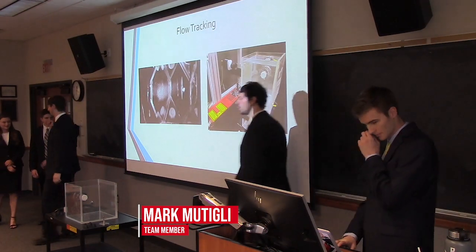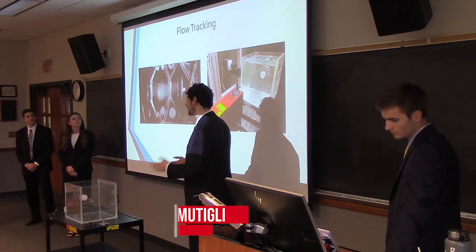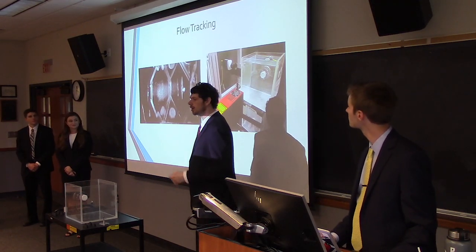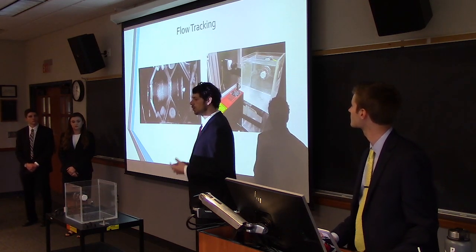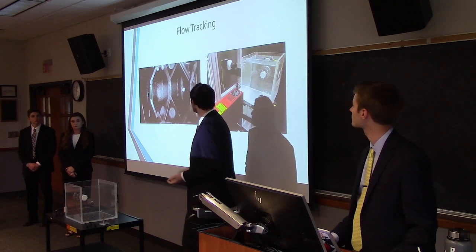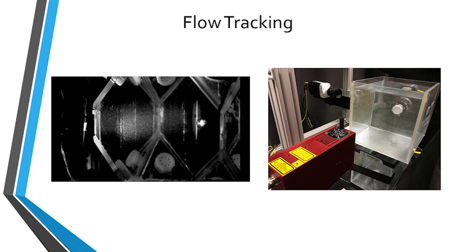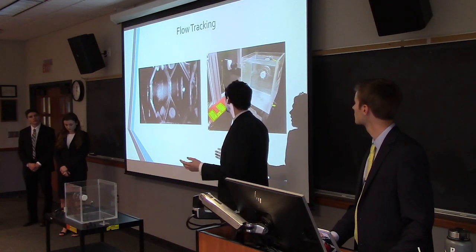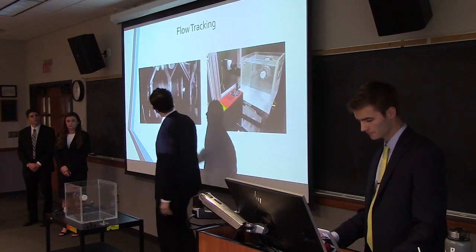All right, now that we can do repeatable experiments due to Evan's implementations, we needed to take data to make sure that we could get consistent turbulence levels and make those turbulence levels uniform throughout the tank as best we could. To do that, we needed to do something called particle image velocimetry, which is just a fancy way of saying we take a laser and a camera, flash the laser, and take a picture at roughly the same time. There are some nuances, but then we get images like this,